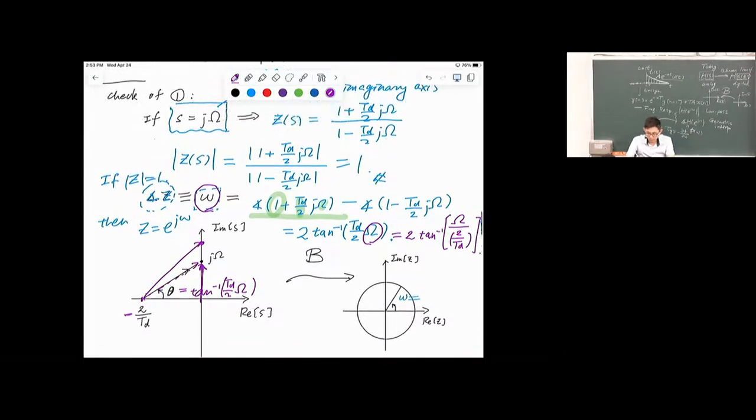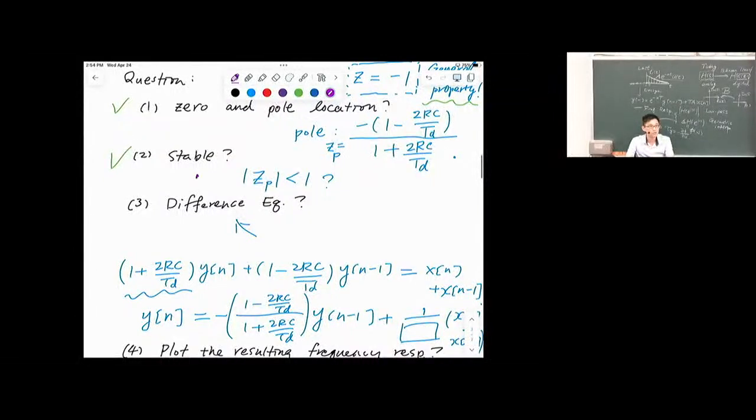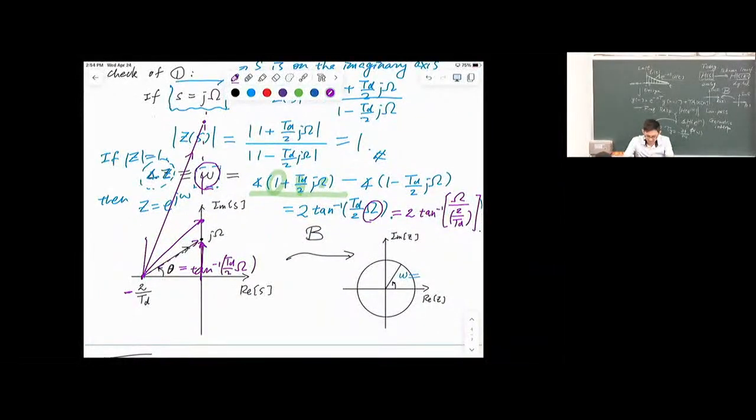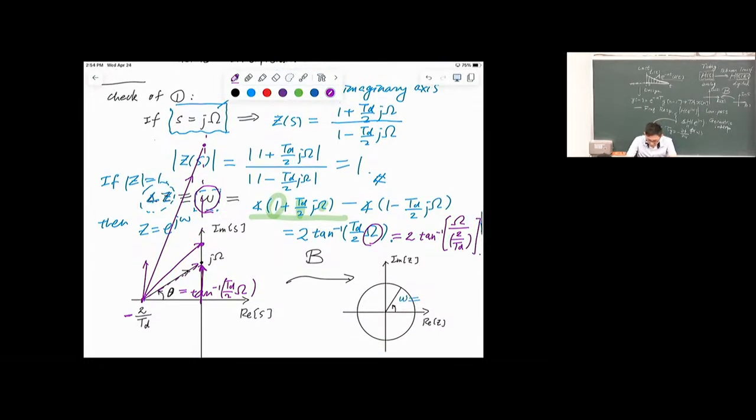When we further increase omega right here, theta increases monotonically, right? And when we further increase omega here, I'm exaggerating, and connect all the way, theta approaches 90 degrees. In the limit as omega approaches infinity, theta of omega is pi divided by 2.